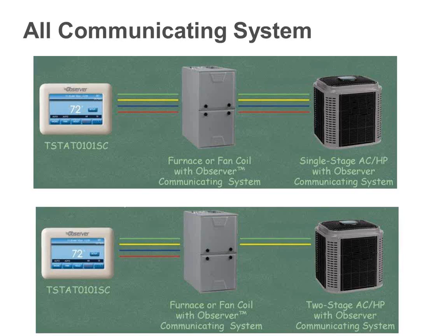I think most of you guys kind of get that. If you're selling a variable speed furnace on comfort and all of that, you probably are also going to want to talk about two-stage equipment with your customer. But it does make it easier to install because, as most of you know, existing installations already have two wires in the wall, not four, so it's easier to use a two-stage unit in these cases. So that would be an all-communicating system, and that's pretty straightforward, I think. You need either two or four wires out to the condensing unit. If you're pulling a new wire, just always pull four. It's pretty easy to think about it that way.